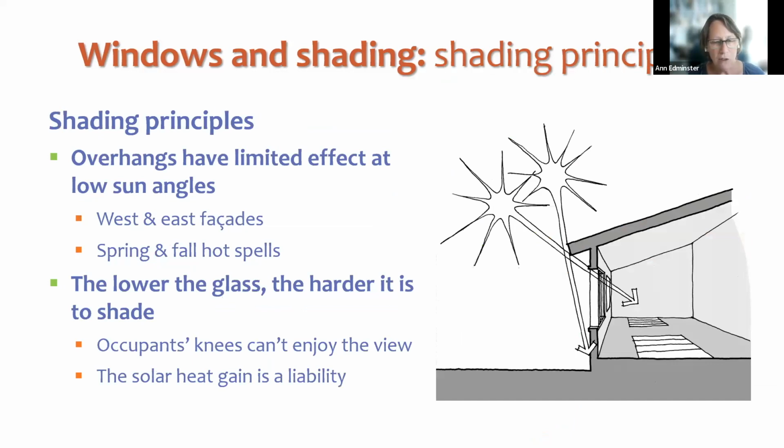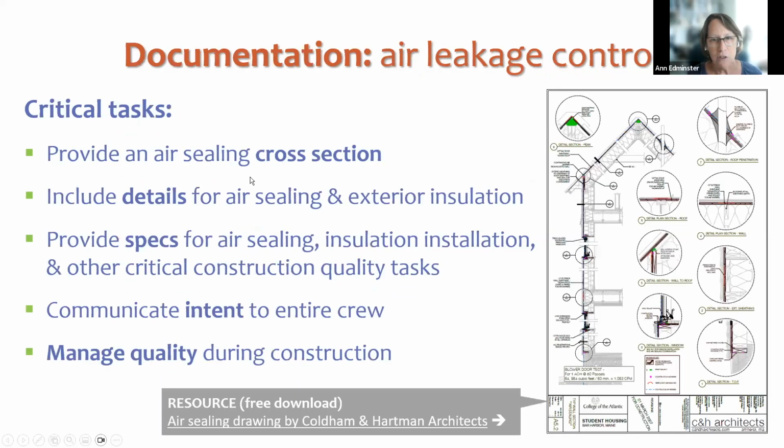And again, you'll see here my favorite point, occupant knees don't enjoy the view. Lots of people love in custom homes floor to ceiling glass. The lower the glass is, the harder it becomes to shade effectively and is absolutely nothing but a heat gain liability. So really want to encourage more attention to shading than I often see in new construction.